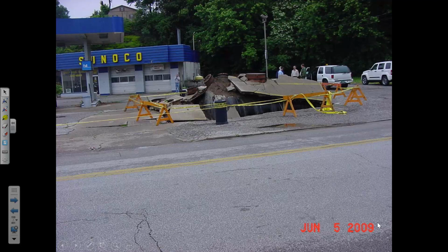And this gas station was closed, and so there wasn't any fuel in the gas tank. So that's an important thing. Anyone want to speculate what happened? You're right, but explain. Go into more detail. Why did the groundwater raise it? Because the tank had a lower density than the water in the ground, and as the water level rose, the tank rose. All right, so when it's wet weather, the water level underground rises and falls.